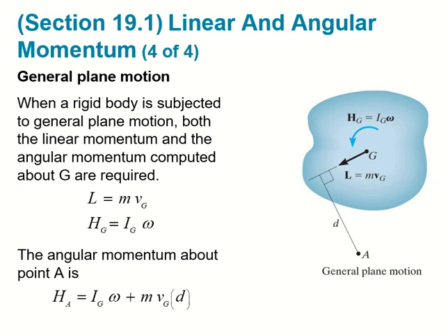We're going to try to get this one. So the distance you will measure from here to here. Of course, you can use your Pythagoras theorem. You can also use a regular measurement. So it depends on the condition given to you. What's most important here is for you to be able to see that you can calculate the momentum at any point A by measuring from the point G. All you have to do is add all the momentum: the momentum due to rotation, and the other one is the momentum due to translation.